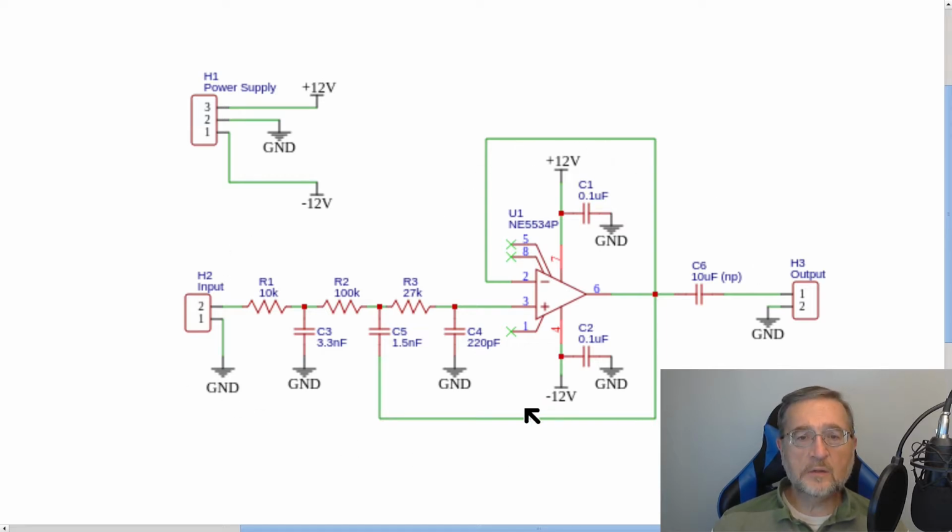It is a third-order low-pass filter obtained by putting in series a passive first-order low-pass filter made of R1 and C3, and an active second-order filter made of R2, R3, C5 and C4. The calculation of the components of this filter is relatively complex, so when we design such filters we start from defining certain parameters that highlight certain aspects of the filter with respect to others.